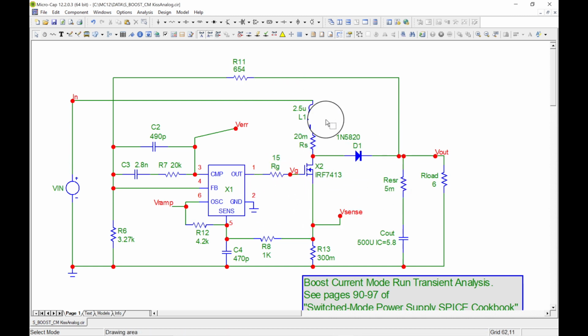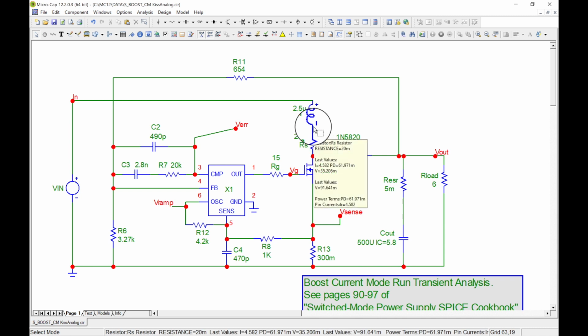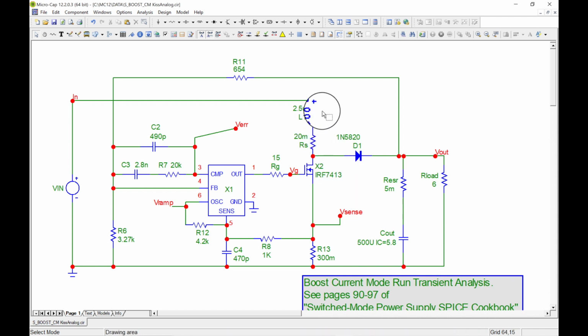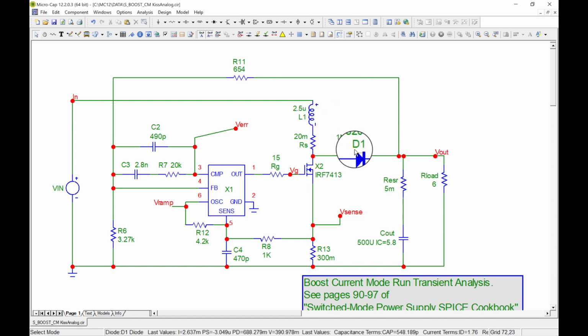And if you guys want the next video for me to change the values to look like the circuit board that I tested in the link below, then we can see how closely this resembles that, I'll do that. And it had 12 volt input, I think a 6 microhenry inductor, and we can change the FET, diode to be more like what's on the board, current sense resistor and so on.